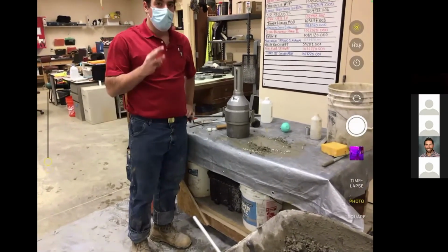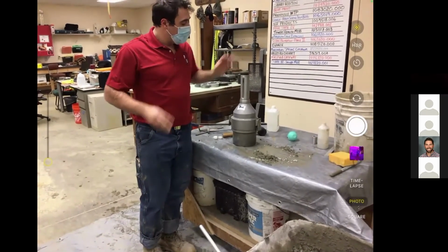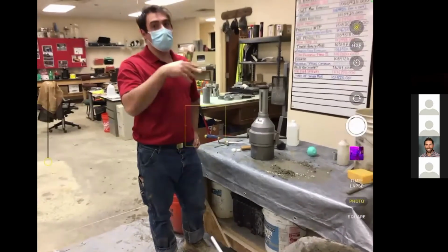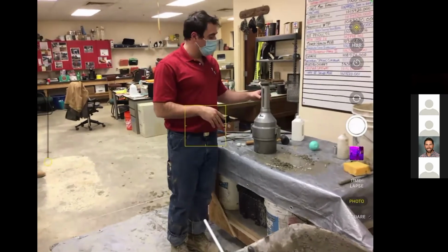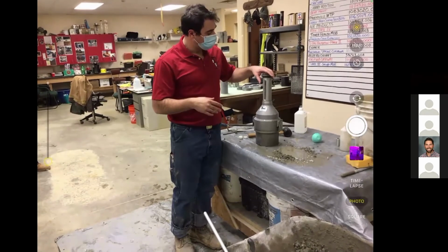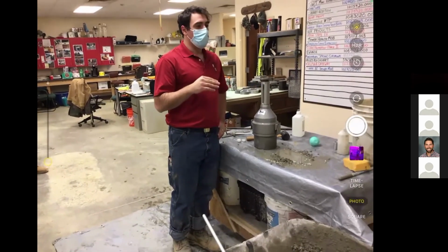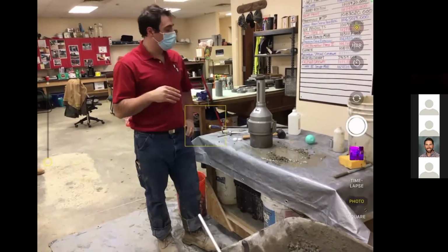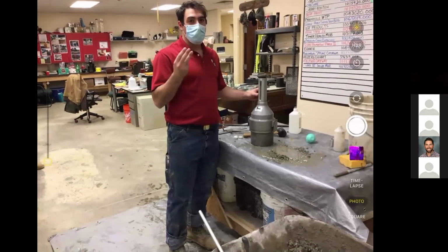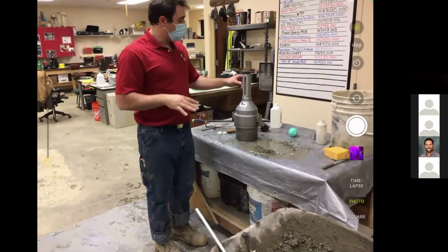Now, if you're repeating it for the third time, you would have taken your second reading as your new initial value. And then we'd be using this third reading to find our final value. Again, if the water level has changed no more than 0.25%, we can take that as our final reading. If it has changed more than 0.25% after our third roll, the entire test would be invalid and we'd have to repeat the whole thing all over again.